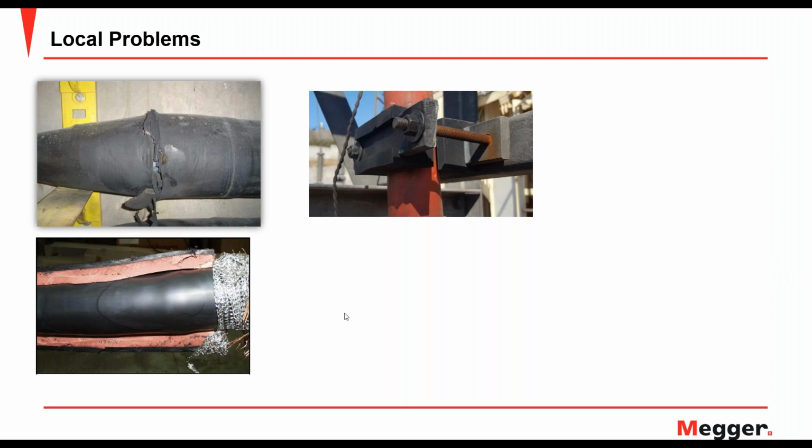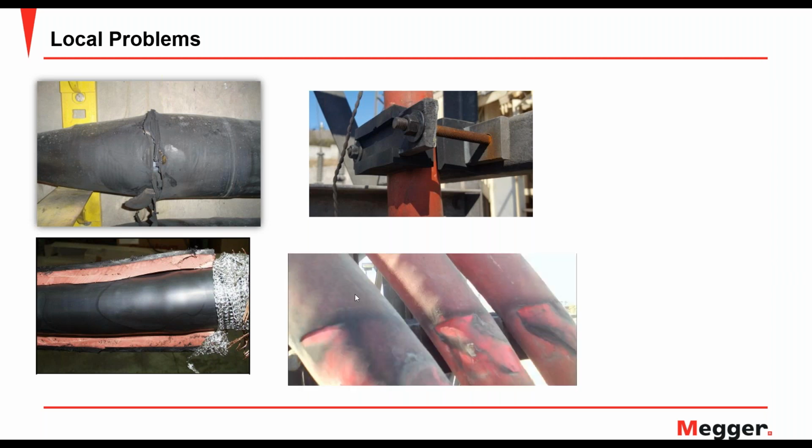Next is an example of clamping a cable. You just have a cable clamp to hold the cable in place. Now these are supposed to be specified to a certain torque. You shouldn't over torque these to cause damage. In this case, there was too much force put on these and it ended up causing damage to the cable. If we look, we can see all three cables were over torqued, therefore permanently damaging the cables.